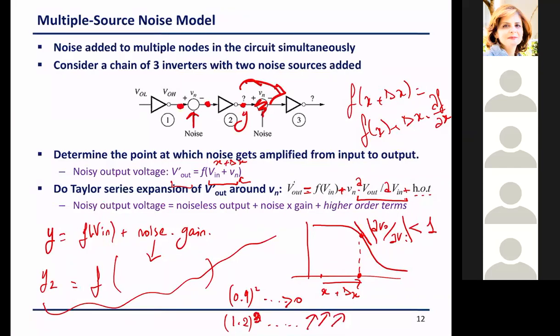So the concept is that the gain entering here is getting multiplied by other gains. If I am allowing myself to operate at small gains for the noise, then it will diminish. Else, if I operate in the high gain region, I can sustain maybe up to this point, but eventually over many stages it is going to come back and explode. Okay, so this is the basic concept.